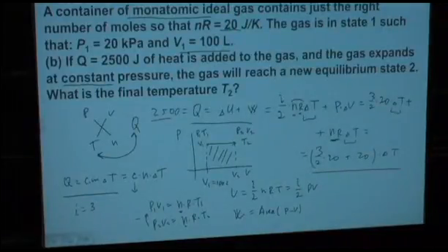So that's the beginning of my equation, and that's the ending of my equation. And, well, so what does it give us? 20 divided by 2 is 10. Times 30 plus 20, 50. So 250 joules equals 50 times delta T. So delta T, the change, equals 50 degrees.